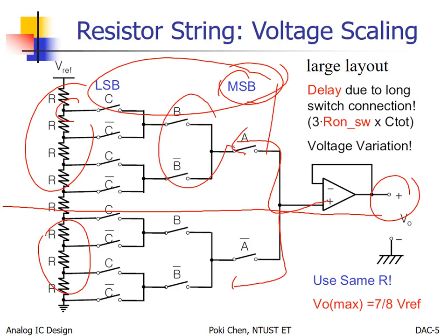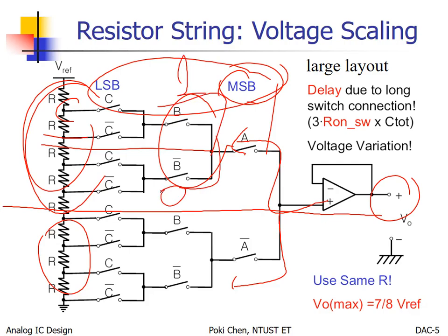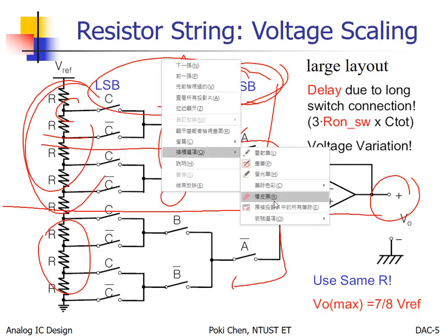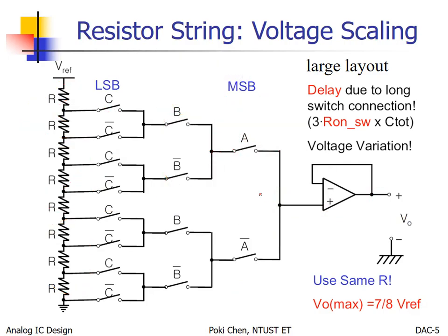No worries. You split this into another 2 halves. The upper for 1, the lower for 0. That's it. Bingo. Very simple idea. So in this way, the circuit is really easy to implement. But what is the problem? According to the breakpoints, your breakpoints will become 0, 1 LSB, 2 LSB. It doesn't make any sense, right?